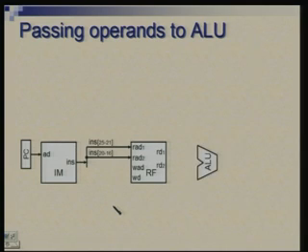So, we have an ALU, imagine the same design which we did a couple of lectures back, where by specifying some control signal you could perform addition, subtraction, AND operation, OR operation, you could do comparison for equality, and comparison for less than, for the purpose of SLT. The same ALU we are putting now as a black box. We are not looking into details of what is inside; we understand that design and we are simply using it to build a larger circuit now.